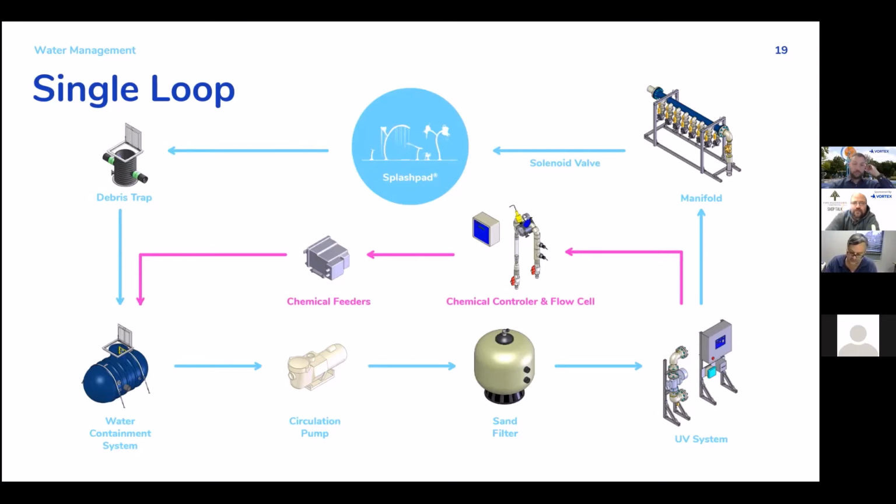Is there a maximum output that this kind of system would be able to support? Like the number of fixtures or things like that? Yeah, so as soon as we switch from a 2,000 gallon tank to a 3,000 gallon tank, we're going to be using a double loop system. And we switch to a 3,000 gallon tank as soon as we exceed about 150, 165 gallons per minute.